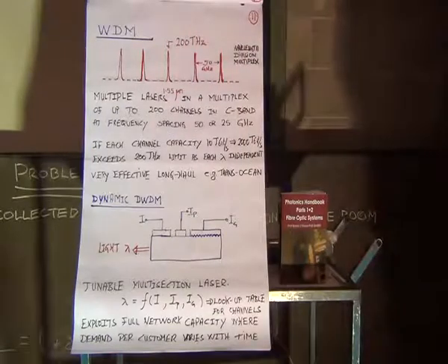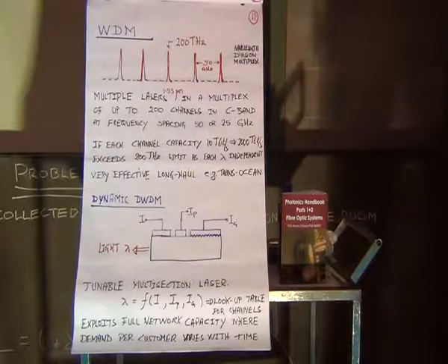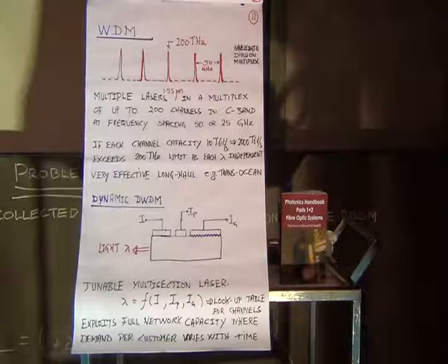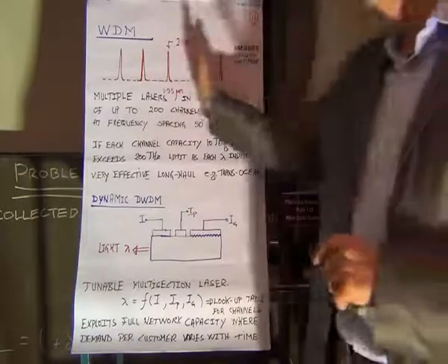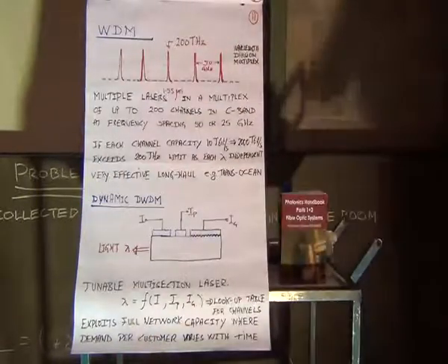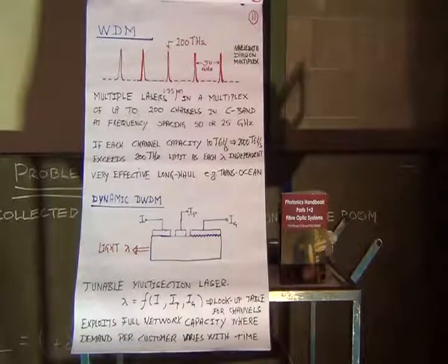That's called band gap engineering. It's quite an achievement. It's working out the solution of the Schrödinger equation in the crystal, working out the exact energy levels, and what alloy mix must I use to get a slightly different fraction of electron volt of band gap, and that will give me the right wavelengths. So there's another bunch of PhDs in doing all that band gap engineering, solving the Schrödinger equation in the crystal.